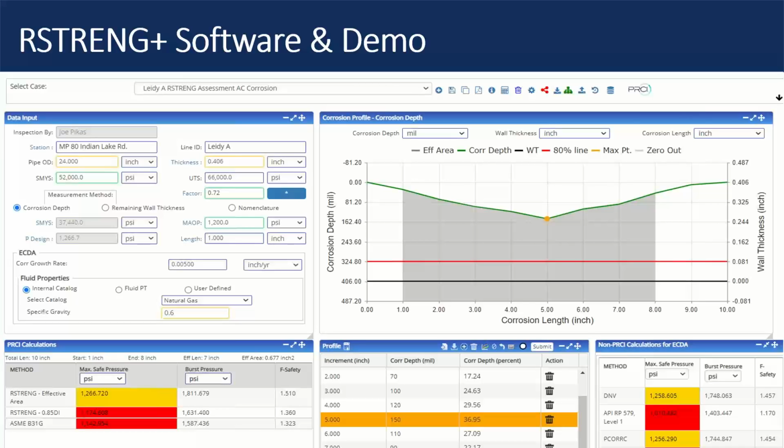This is a typical pit that you would see, typical V. This is why B31G used something like this as normal galvanic type pitting. But guess what? We have other factors out there called stray currents, whether they're AC.